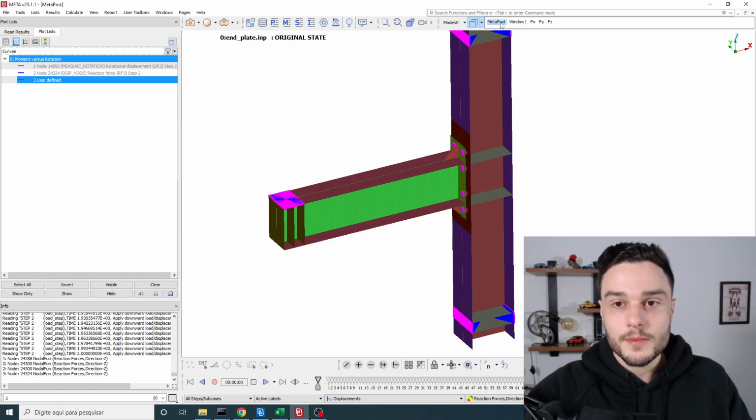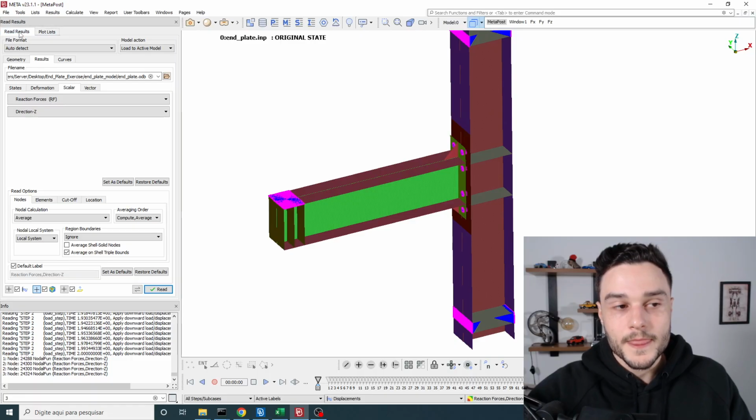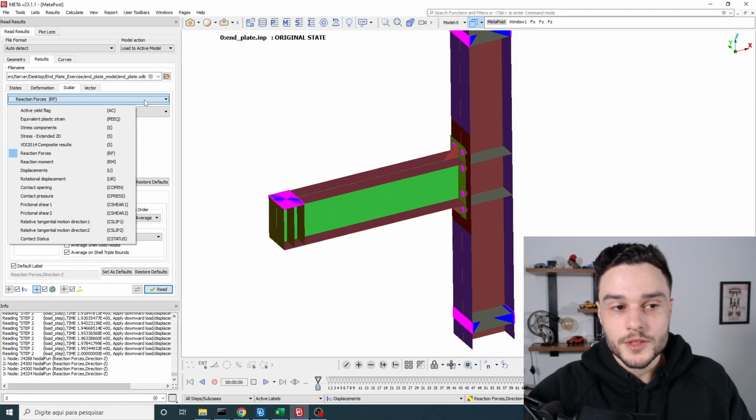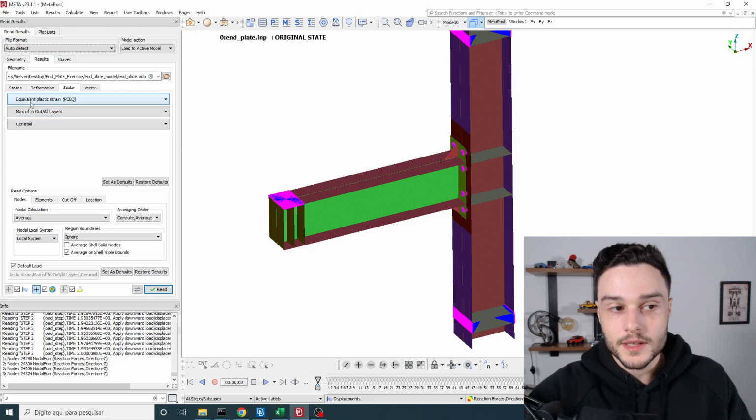So let's go back to the meta post tab here, read results, and results scalar. Before I started this video, I have calculated some other results. So just for you to have the same thing as I have here, first of all, calculate equivalent plastic strain.